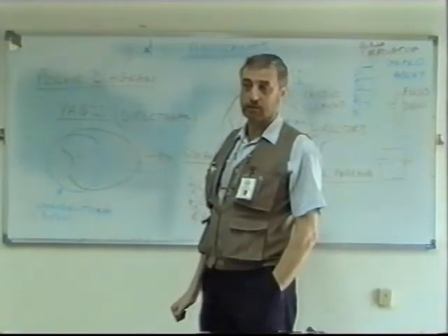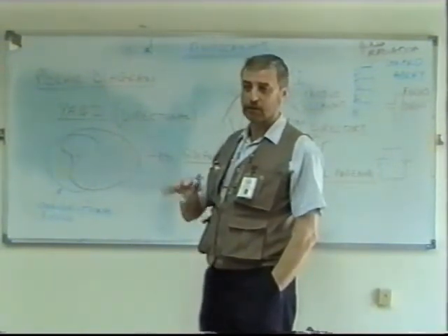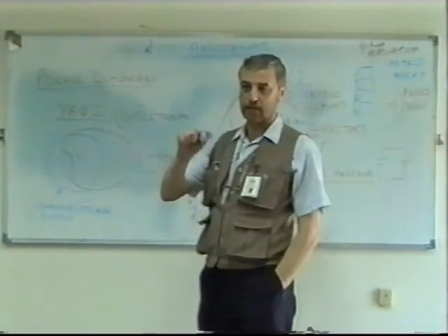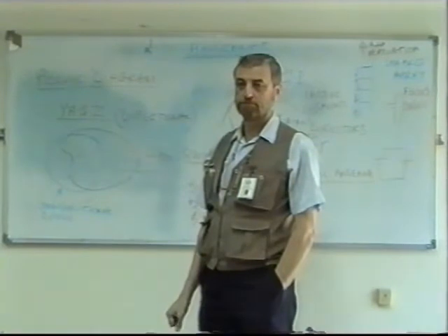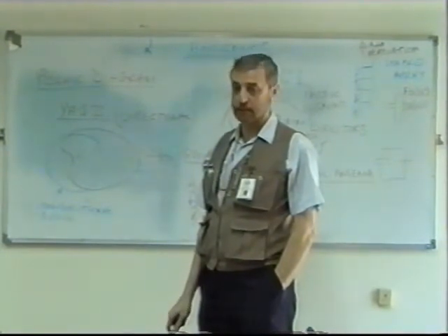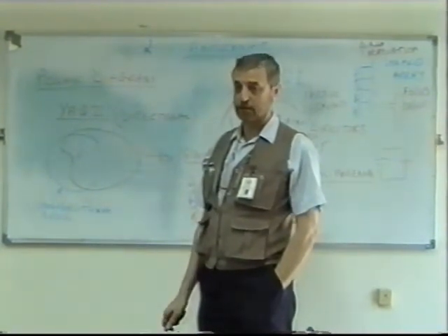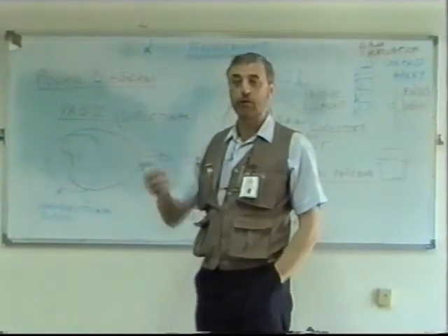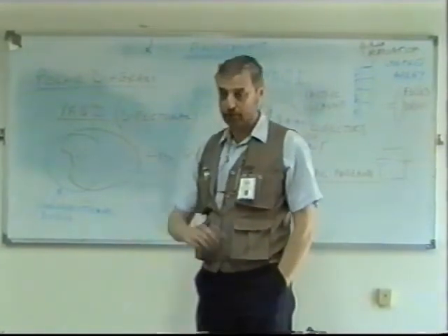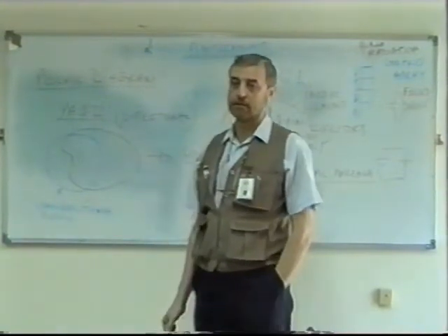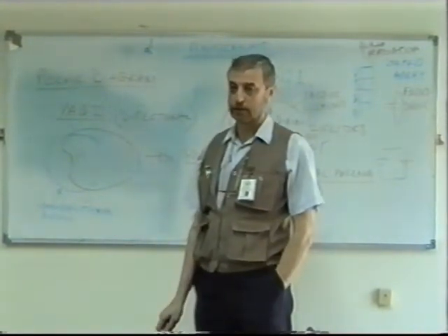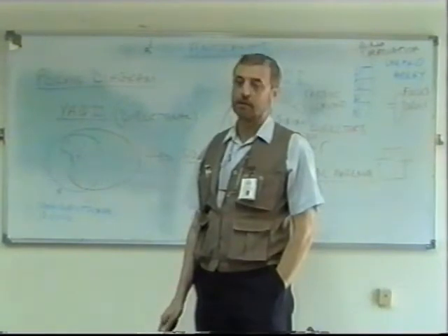It could be a quarter wave, but I don't know really, because I'm not familiar with it. I'd have to look at the length and know the frequency. A quarter wave needs to be grounded, yes, because you need a dipole. You're only using half a dipole, so the rest of it must be from the ground. The other side of your dipole is in the ground. In a full dipole, you don't need the ground.